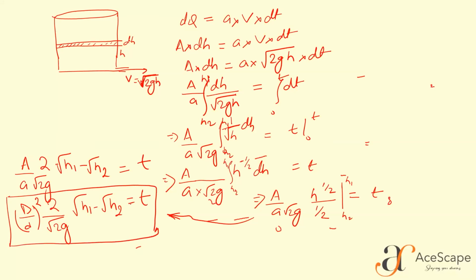Here we can say one thing also, that the time which is required to empty or maybe fill the tank is directly proportional to the root h. After integrating, we got that it is varying on the half power of h. So it is also a relation which can be kept in mind.